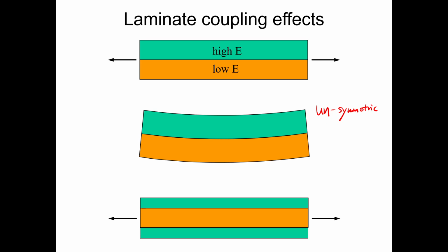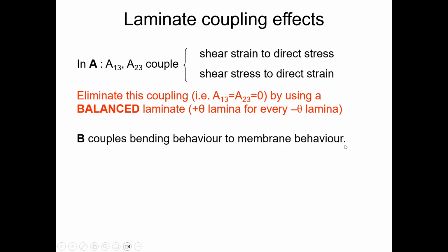Or non-symmetric. But if you put something in between, at the middle layer, and this is symmetric, this will lead to B equal to 0. As long as you substitute your values into our equation for B, where you have the K, ZK and ZK minus 1, you will find that if you put in symmetric layers, this will be equal to 0.